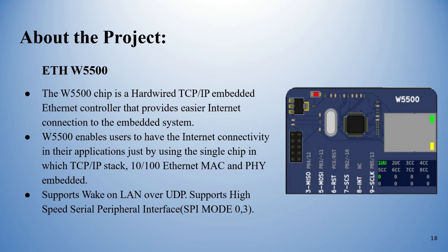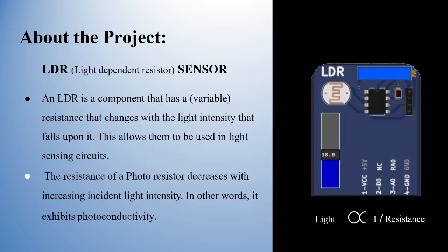The W5500 chip is a hardwired TCP/IP embedded Ethernet controller that provides easier internet connection to embedded systems. The W5500 enables users to have internet connectivity in their application just by using a single chip, in which TCP/IP and 10/100 Ethernet MAC and PHY are embedded. It supports Wake on LAN over UDP and a high speed serial peripheral interface.